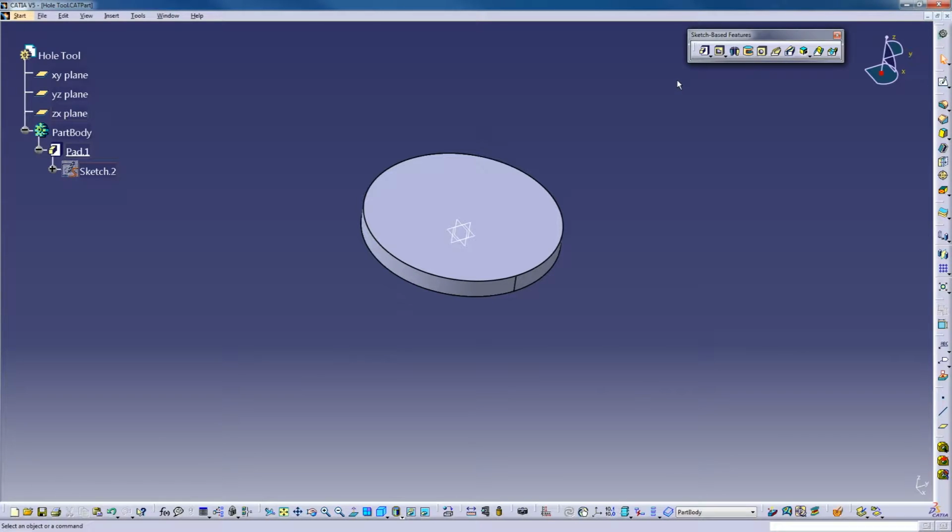There is actually a way in CATIA that you can make a hole, or any of the negative features, without having anything solid first, which is really a little bit of a brain fry, because it's kind of like you make a hole in space, and then what ends up showing up is actually a solid instead of a hole. It has to do with what they call positive and negative part bodies, or part body polarity. It's really pretty interesting. I can't say that I functionally ever use it, but that'll be something we talk about. It'll probably tie in best with when we do Boolean operations.